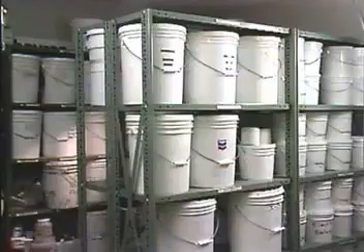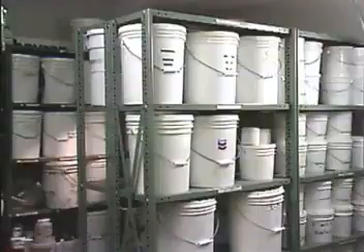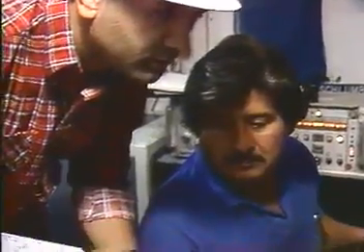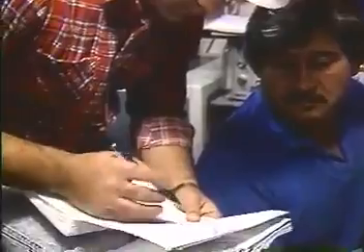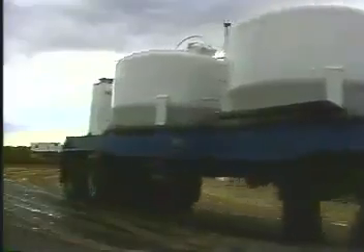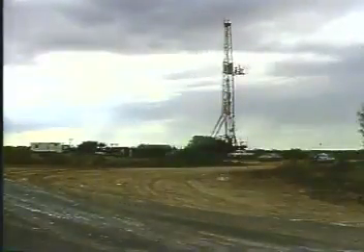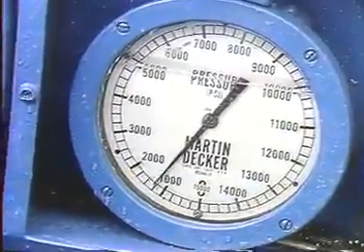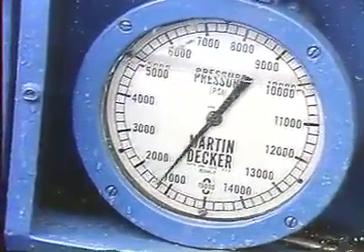Be certain to select the correct classification of cement depending on hole conditions and strength requirements. Calculate slurry volumes using a caliper log and increase by an appropriate safety factor to avoid under-cementing. Pump plugs before and after the cement to ensure proper displacement. Maintain tension in the string while the cement sets. And remember to pressure test the cement job prior to drilling out or perforating.